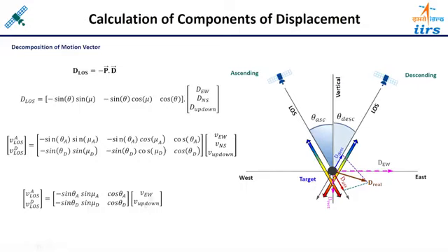Here you can see this is the horizontal velocity, this is the vertical velocity, and these are factors depending upon the incidence angle and the azimuth look angle, which are known. So these are two equations. These values are known because the data was analyzed from both passes, and the factors are known because incidence angle and azimuth look angle are known.